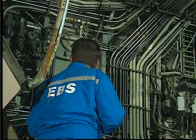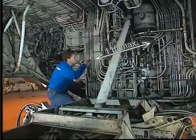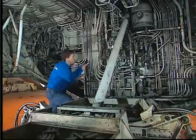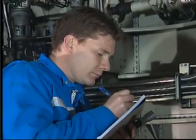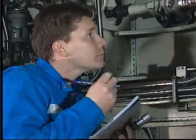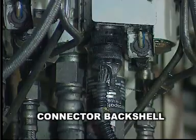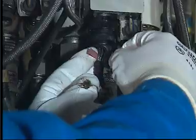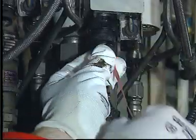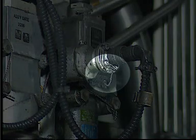In a general visual inspection, you must stand at a very short distance, less than 1 meter, from the parts to inspect. All the visible defects must be noted down. For example, the attachment of the conduit in the connector back shell. As you can see in this case, the cable tie is missing. In this case, the lock wire is broken and must be replaced.